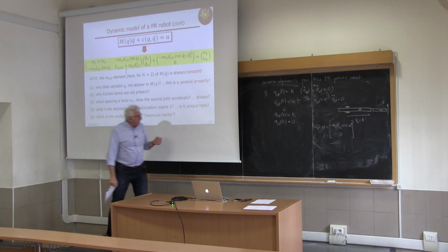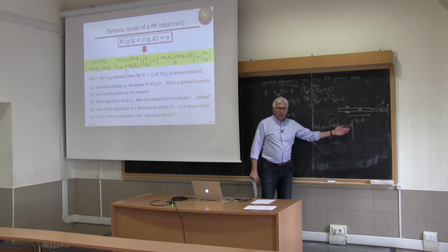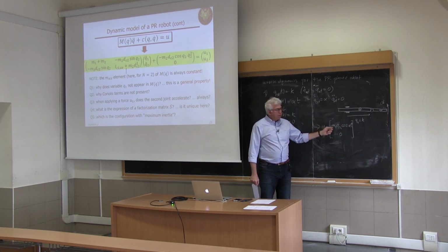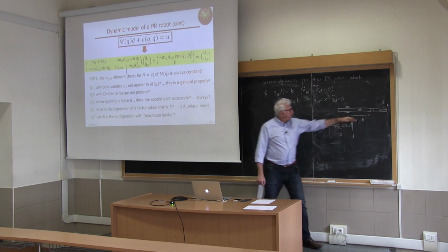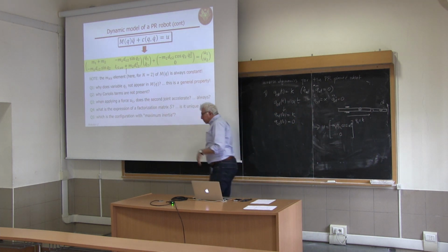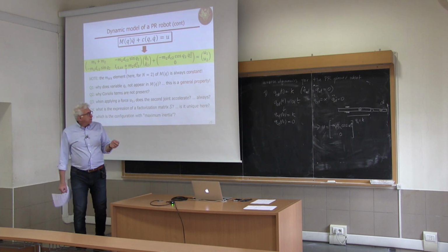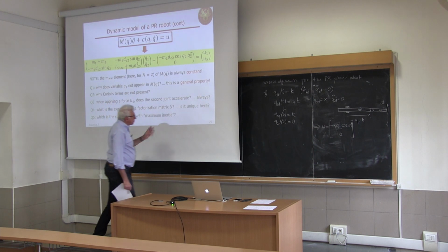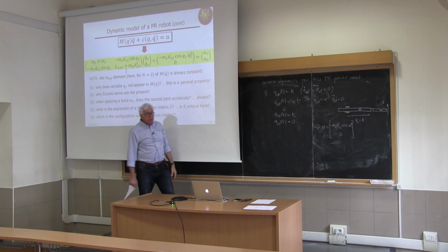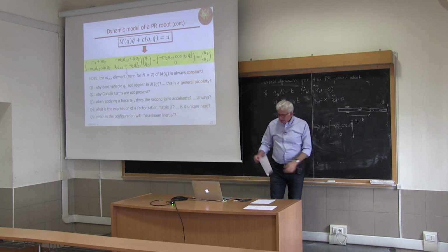And you see that it has the same angular profile of the speed here, and it has a minus sign because it contrasts the effect of the induced torque. This is an inertial effect that needs to be compensated. Actually, sorry, it's not an inertial effect. It's the effect of compensating the centrifugal terms, the quadratic term.